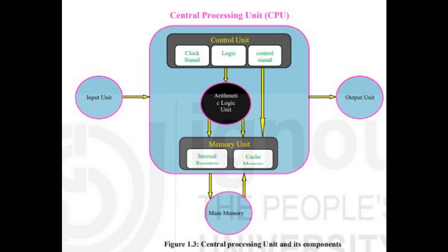Instruction register, IR. 2. The instruction in the IR is interpreted by the control unit. 3. In addition to step 2, the operands are brought from the main memory to CPU registers. 4. The operation as interpreted at point 2 is performed on the data obtained in step 3. 5. Results of the operation in step 4 are stored in the CPU registers. In case the instruction specifies that the result of the operation is to be stored in the memory, then the result data in CPU registers are transferred to the specified memory locations. The execution cycle is repeated as long as there are more commands to be executed.